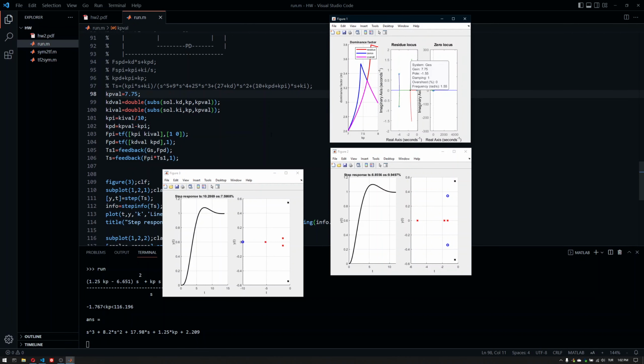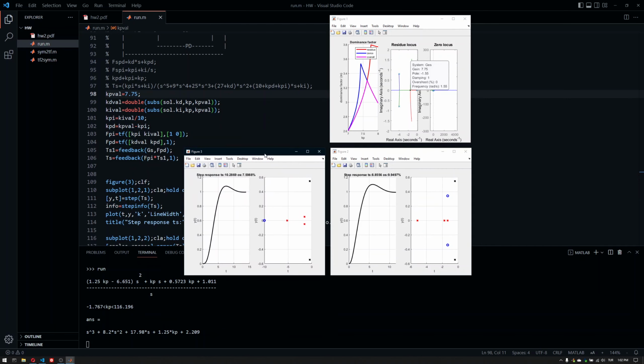It almost did the job, but I just wanted to choose the actual point on the root locus. So basically, due to the residue poles, this point is the best I can get, basically. So here we can see this is the furthest point for the residue poles, and I've chosen that one here, but still the system has not the best dominance factor at all. It is approximately around, what is it now, 3.8.